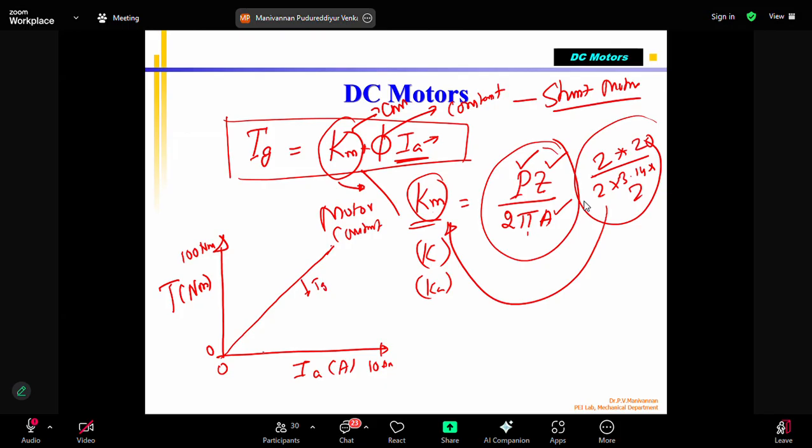But in the shaft, I told you there are mechanical losses, bearing losses. All the torque generated by the motor, because of the repulsive force created by two magnetic fields, which depends upon the voltage applied, the current flowing in the coil, and also the magnetic property, Km, motor constant, design, poles, is not delivered to the shaft. In the shaft, it will be a little less.